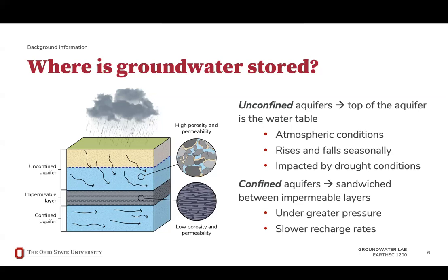On the other hand, confined aquifers are overlain by a confining layer, usually an impermeable rock or clay. The water in these aquifers is under pressure, creating what's known as an artesian system. Confined aquifers are recharged from specific areas where the confining layer is absent or permeable. They are more protected from surface contamination, but can be depleted if overpumped.